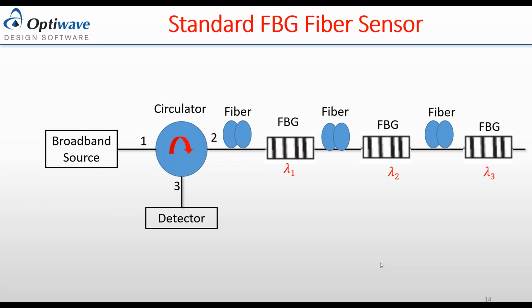Okay. In this part here, the FBG is implemented in the standard form. Again, you have, for example, a source where your location, let's say this station here, is the station where you monitor and you transmit your signal. The signal again could be a broadband source, let's say, for example, an ASE source or LED, transmitted through a circulator. The circulator directs the light from terminal 1 to 2 and through the fiber.